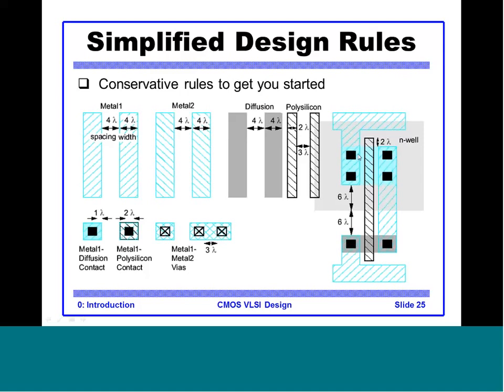So let's look at this. The bottom part is the NMOS and the top part is PMOS. How can we differentiate? We see that the region here is N well. So a PMOS needs an N well to function. So this part is PMOS. The rail here is the metal rail, up on the top and on the bottom. The bottom rail would be tied to ground. This would be tied to VDD.